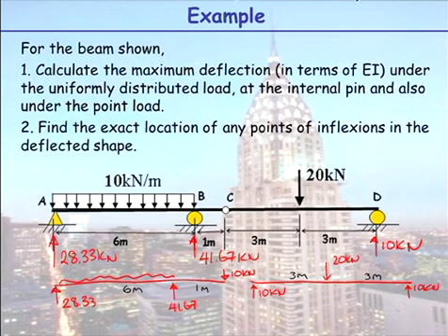Okay. So it's all about deflection now. We're talking beam deflection, and I gave you this problem to do. We worked out, I think we had drawn the bending moment diagram as an exercise in that, and the shear force diagram. Now with this particular problem, there's an internal pin at C. So you have to split the system at the pin at C.